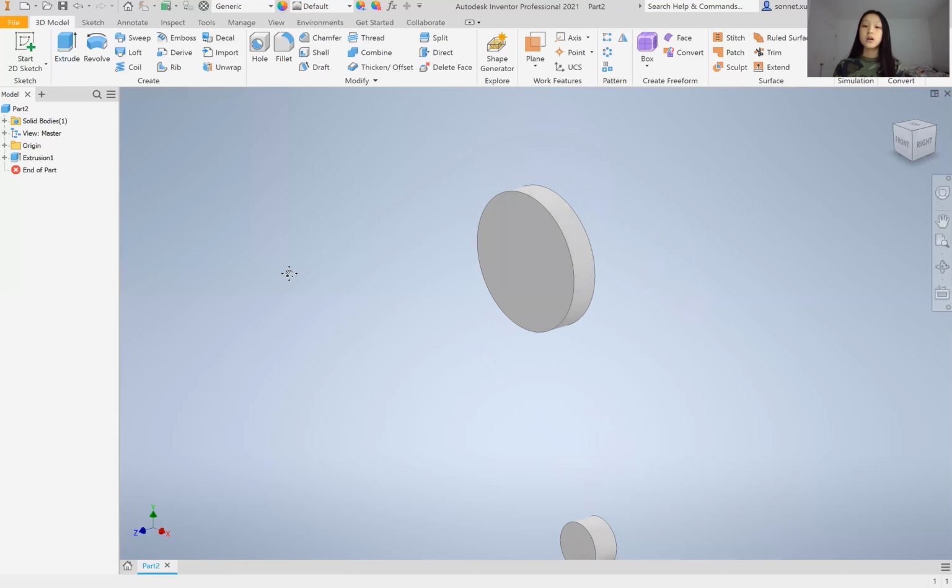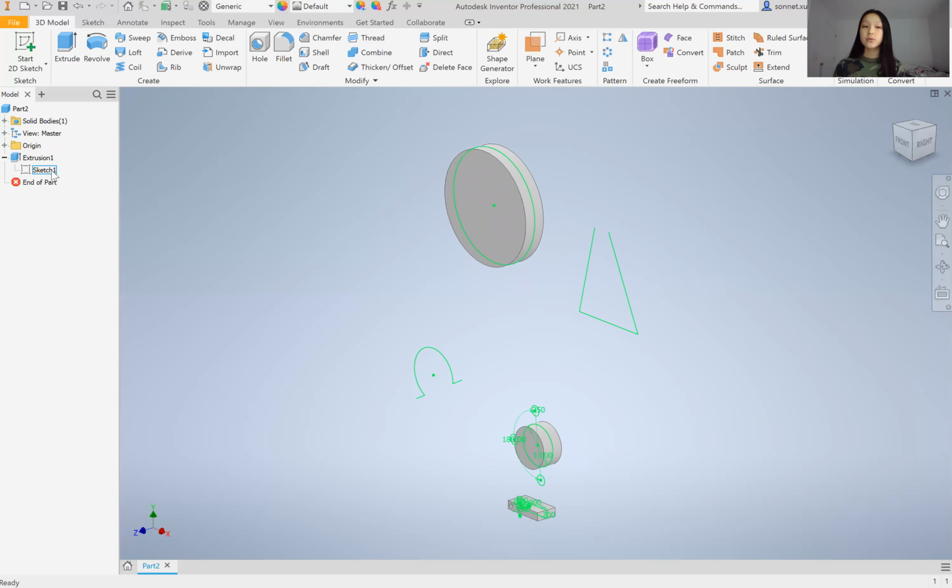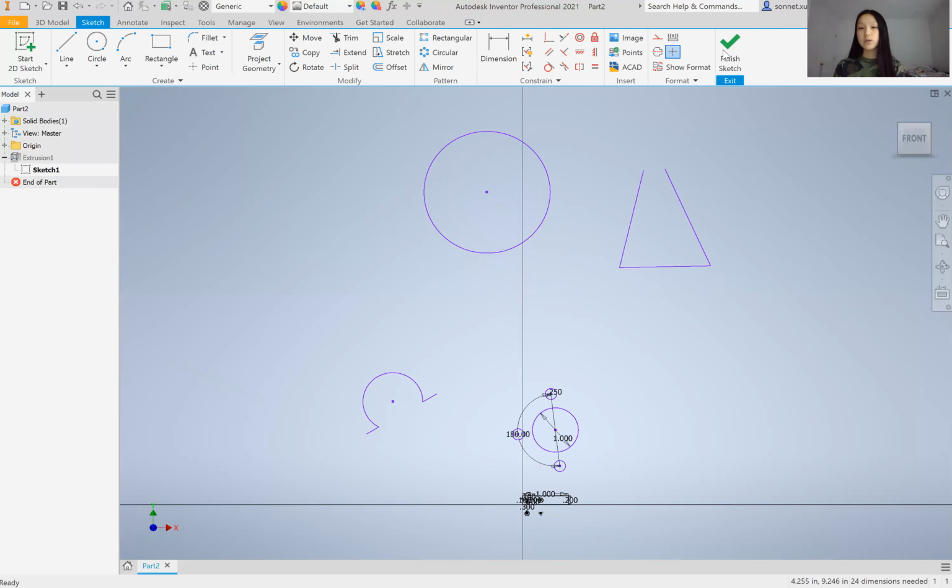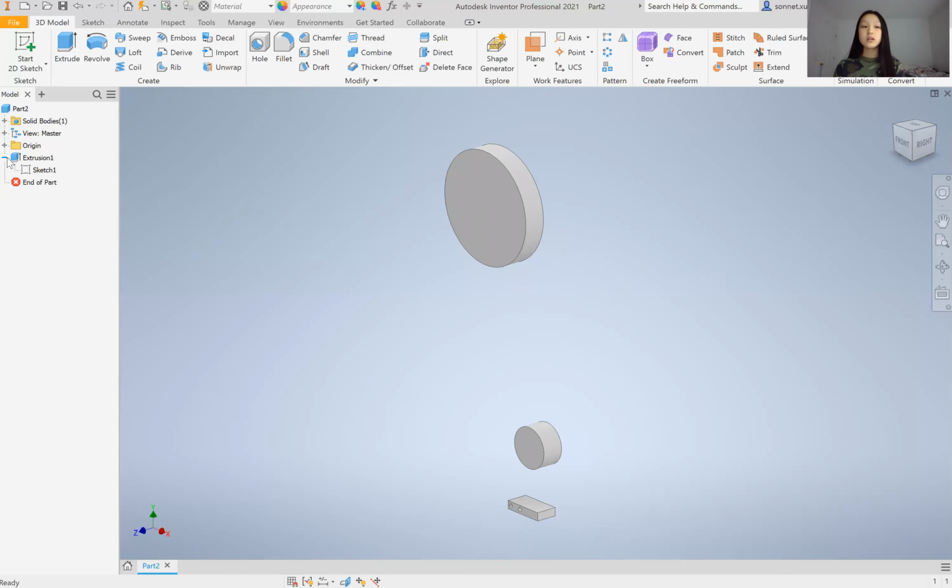Okay. So now you see that I have a bunch of these shapes, and all the sketches that I originally had disappear. If you want to go back and edit that sketch and make any changes, the sketch is available here. Double click, and you're right back to where you were. But if not, the sketch will just hide itself. So in the grand scheme of things, it won't get too confusing to watch. So does the extrusion tool make sense to everyone? Yeah? Okay. So that's good.